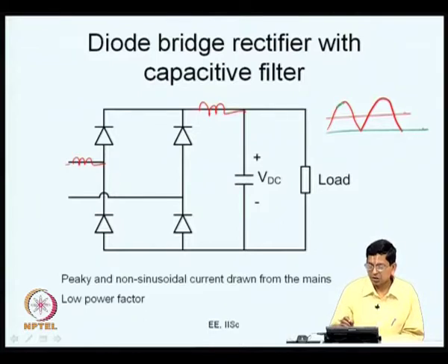the capacitance gets charged over a short interval of time and it discharges like this; it charges up and it discharges like this. The voltage waveform becomes something like what I have indicated in green ink. So, you can see that the ripple in the output voltage is now much reduced, which is what you want. It is basically a power supply. Ideally, it should have a flat voltage without any ripple, which is not possible. So, you reduce the ripple to an acceptable level, and you put a big enough capacitance effectively to realize this, right.